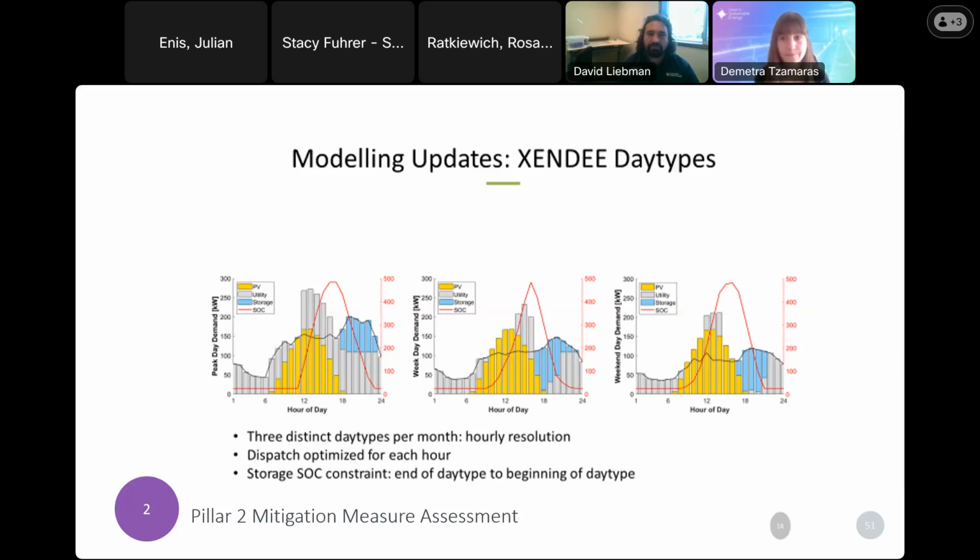It's important to note that the modeling software really gives us the flexibility to test out different technologies and their economic results and optimization. But I will caution that it's really important that you then integrate the model with whichever microgrid controller controls all your assets, whatever engine that controller has, because otherwise you might be left in a situation where you modeled something, but then your actual controllability asset will not operate the same way.